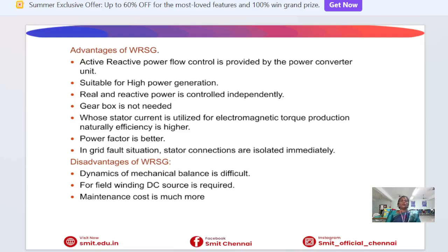The WRSG offers several advantages in modern wind energy systems. It provides independent control of active and reactive power through power electronic converters. It is suitable for high power applications and generally offers higher efficiency because gearbox requirements can be reduced or eliminated. The power factor is better, and during grid faults, the stator can be isolated quickly to protect the system.